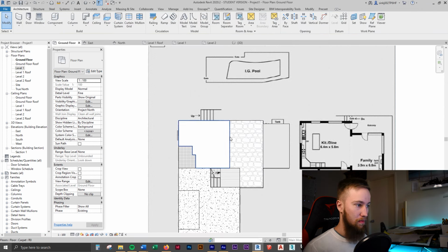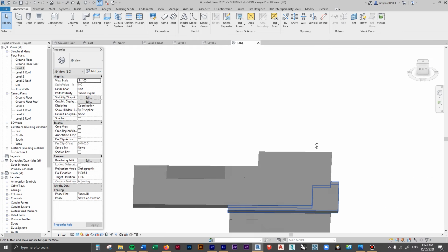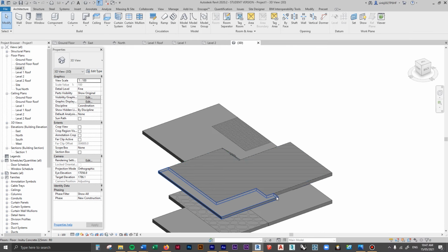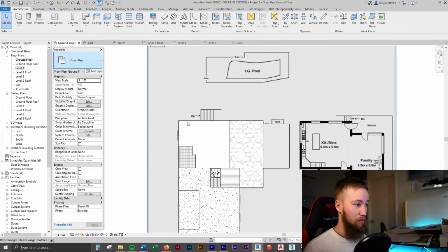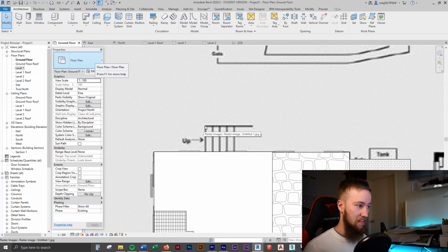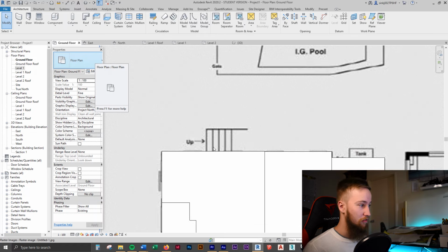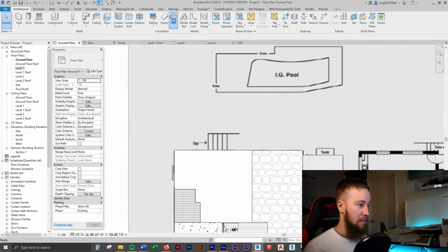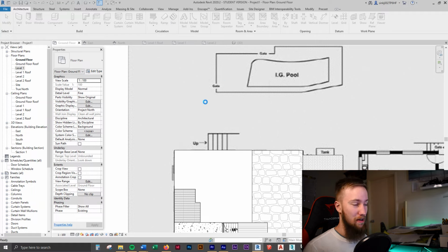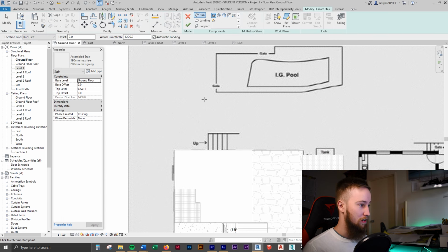So now while we're on this topic of stairs, we can actually go ahead and put in the balcony stairs as well, which are going to go up to this point here, which is the balcony, which comes from the ground floor. If we go to the ground floor plan, you can see that the stairs start here, looking at our reference image. Again, click stairs. Make sure you save your project. I love that Revit automatically asks you to save your projects because a lot of the time we don't save and then we lose a lot of work if our computer crashes.